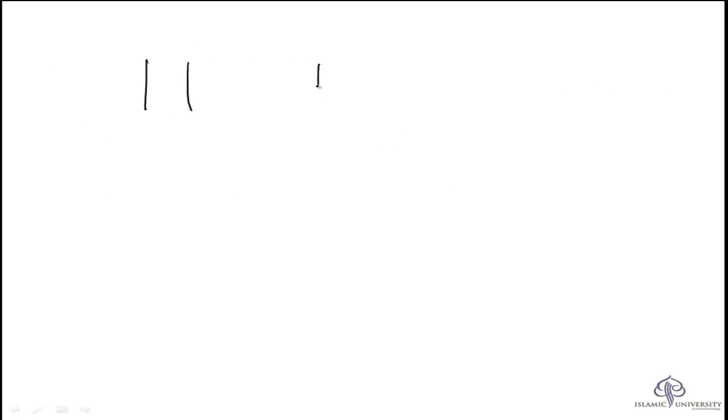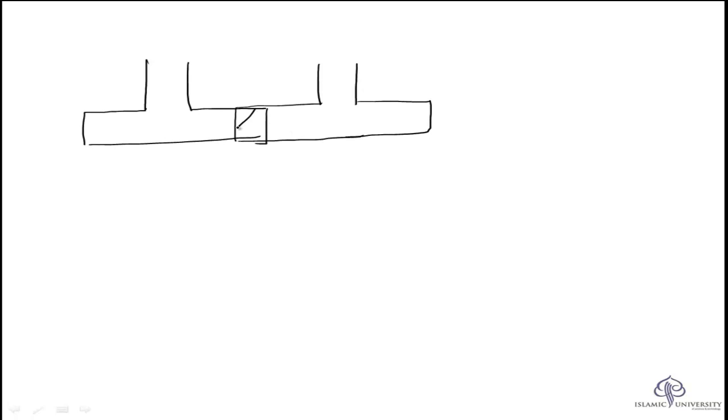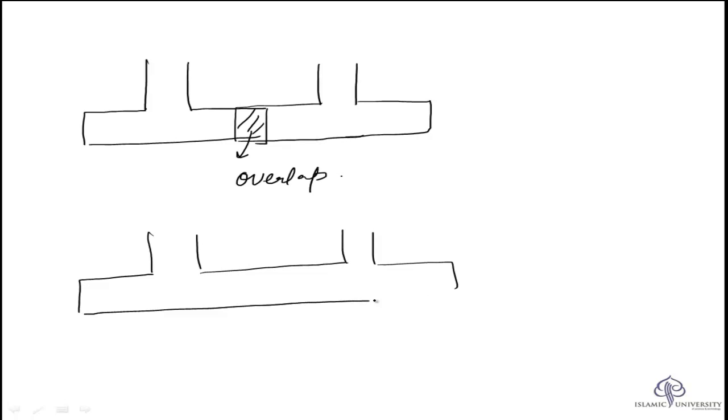All that will result in overlap of areas if isolated footings are provided. This is the resulting overlap. In such a case, it is better to provide a single combined footing for columns instead of providing separate isolated footings for each column.